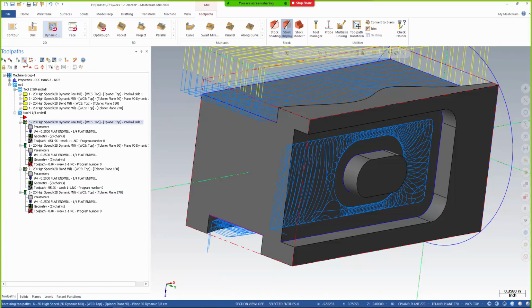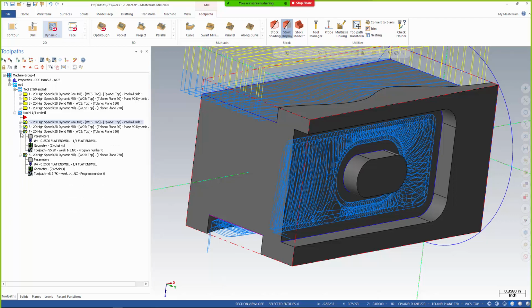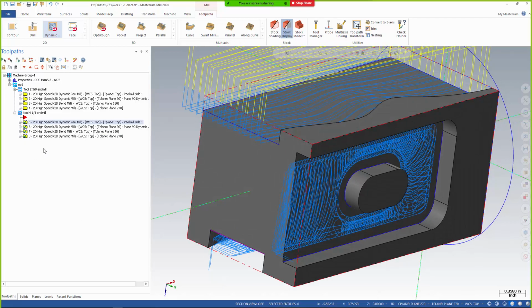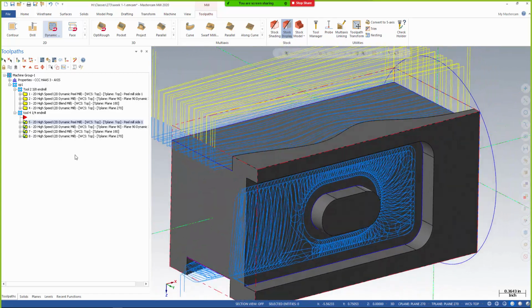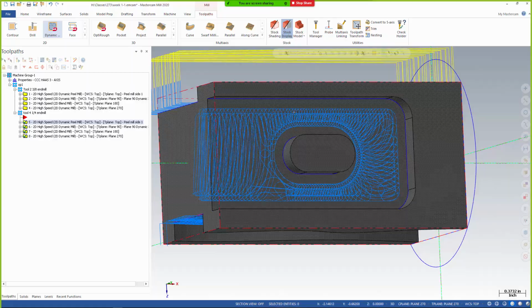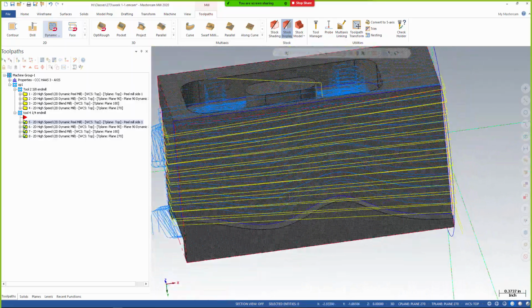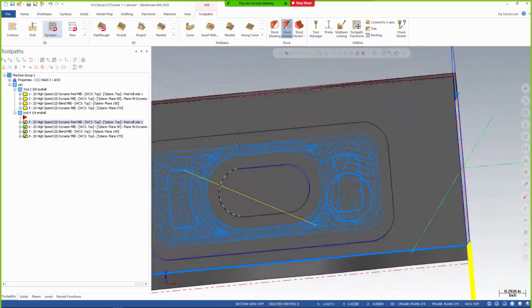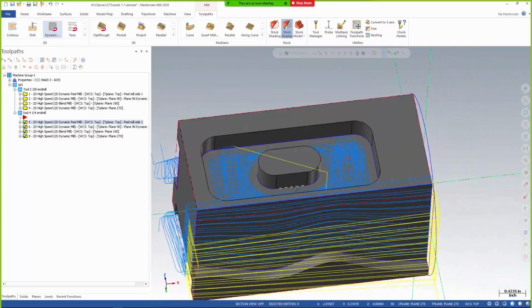Then I'd go back in with another toolpath or another set, and then finish the walls on that, possibly with even a smaller end mill like a 3/8 or whatever else, or possibly another 1/4 or anything that might fit. Frankly, a 3/8 would actually still fit. So I could get in there even on this face. There should be enough room between these two faces to get the 3/8 straight through it without having to worry about anything else.